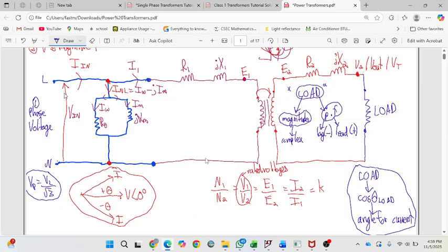Cool. So this is the phase voltage here, and you give your input current. And you know the first place the current is going to go is your no load. So basically think of this as trying to cook: you have to go to the grocery and get all the supplies before you start to cook. That is your no load current. So it's kind of like setting up your magnetic field and stuff for you.